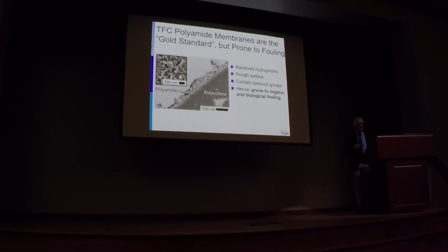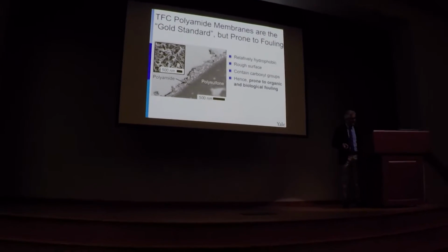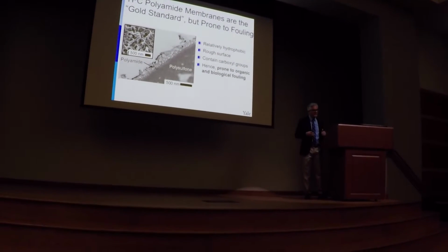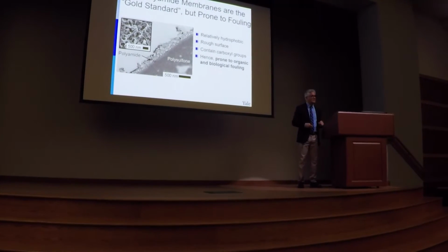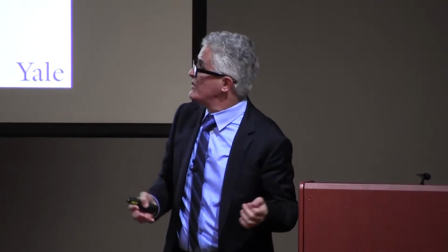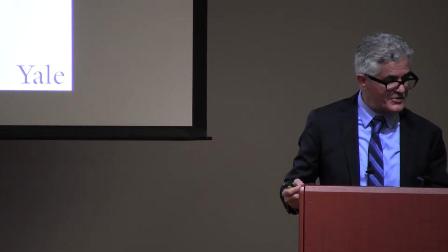So what I'll argue, and I argue it in a review article we wrote a few years ago, is that you can really improve many aspects of desalination by developing a fouling resistant membrane. The way we operate nowadays in a reverse osmosis plant, as you get fouling, the resistance to flow increases, so they increase the pressure because they want to keep the water productivity constant. When you increase the pressure, typically by 10, 15%, it's a 10% increase in energy. So if you can develop fouling resistant membranes, it will help in this aspect of the energy.